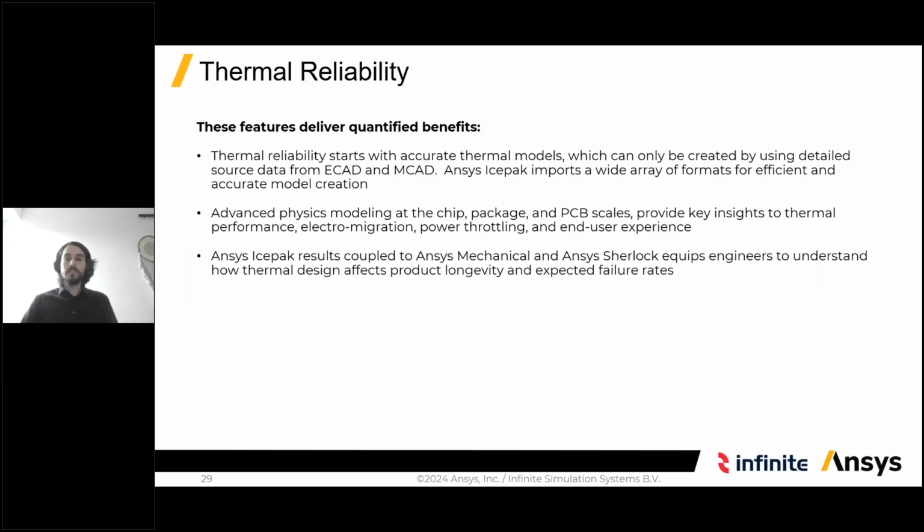So to summarize, when we talk about thermal reliability, we want to make sure that we have accurate thermal models. We have all the details in the system. This is including the mechanical CAD and the electrical CAD. The material properties are also very essential to properly define. We need to understand how much detail our models should have, because thermal reliability can be measured at any scale, from chip to the whole system.